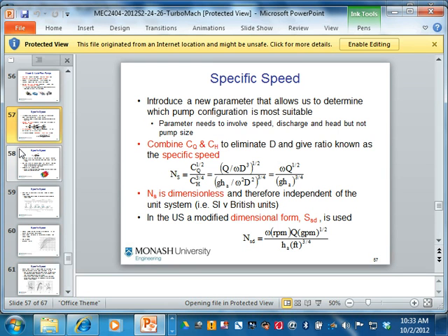Basically, in there there's Q and there's H, so it's a ratio of Q over H. Q is the flow rate, either volume flow rate or m dot, and H is the head. So with high flow rate, this number will be big. With high head, this number will be small. Right or not? Okay?